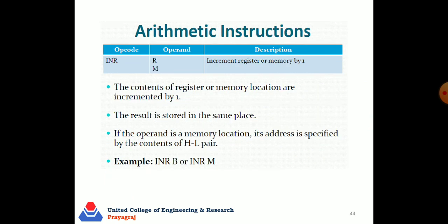After that, it is INR. What is the meaning of INR? It is increment register. INR, it is the increment in register. The register may be A, B, C, D, E, H, L or memory. So after executing this instruction, whatever content is in the register is automatically incremented by 1.